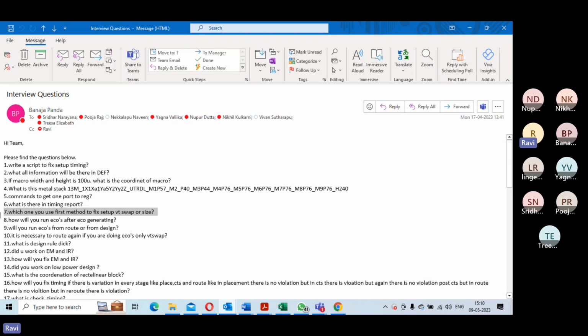Now when we are doing timing issues, timing issues can come in various ways. Let's say they have added big cells. Then you will look at creating space in that local area, whether there is space. Then you will source that and try to do the placement, legalize it. Then you will do incremental route, so that there is no short. Then you will clean and take it to the final cleanup. That's how you are going to run the timing issues.